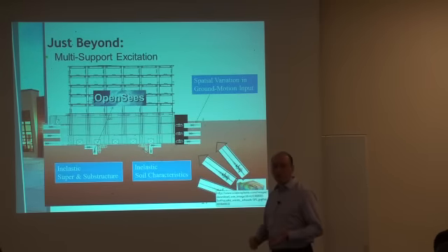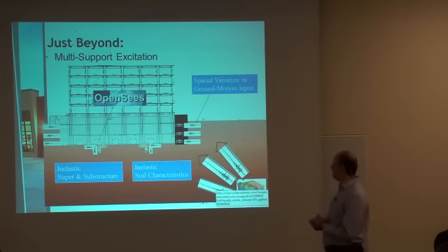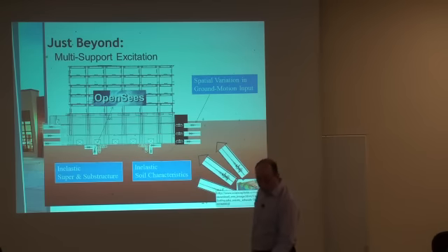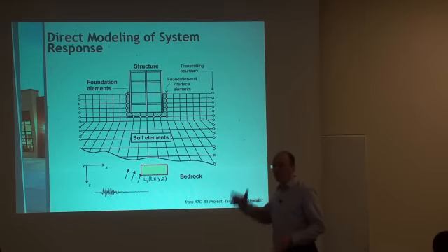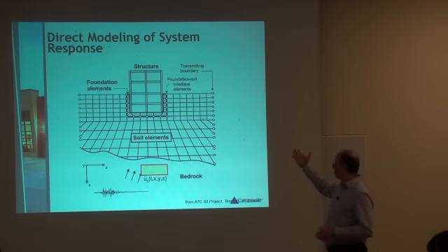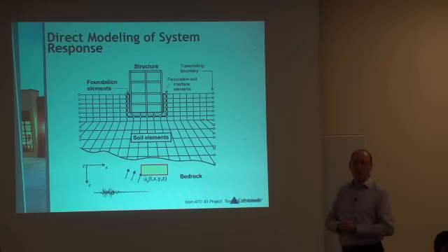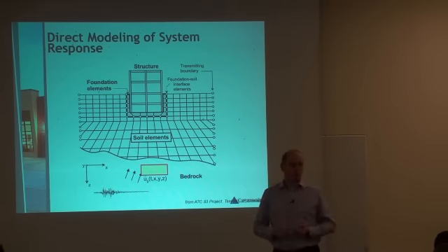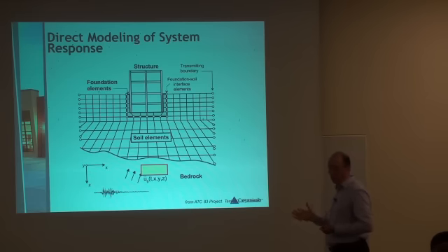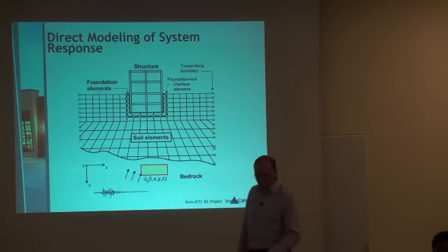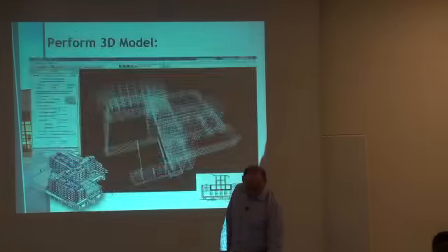Now, moving to OpenSees, which we're trying to do, allows you to overcome some of these limitations and go much further. So one thing you can do is multiple support excitations. You can get better representation of soil springs. Eventually, we want to get there. While explicit modeling of the soil may be feasible now in the research, it's still not practical in practice, because a model like this could take days, maybe weeks to run, and we simply cannot afford to do that, but we hope to get there eventually.